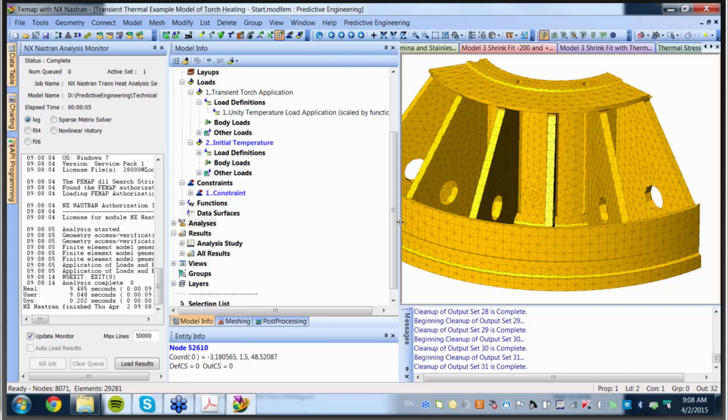So the way we did it is that you can use a film coefficient. Think of the film coefficient as a pipe. You can open up the pipe or choke it back. So we used the film coefficient to ramp the temperature. You just have the temperature go up, film coefficient full, and then when we wanted to turn off the temperature, we just turned off the film coefficient. Think of it like a floating boundary then. So that worked out real well.